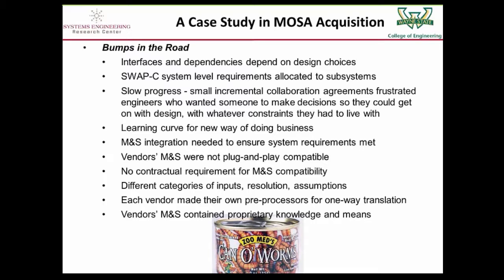So we said, fine, we'll add up all that. Here's the new weight goal. But that didn't work either, because at the higher weight, the engine has to be bigger, the suspension has to be different, we need a different number of road wheels on the drive, and we're bigger, so we are going to need more armor, and the weight goes up, and you go through an iteration again. So even if they're not entirely emergent properties, they're system-level properties.